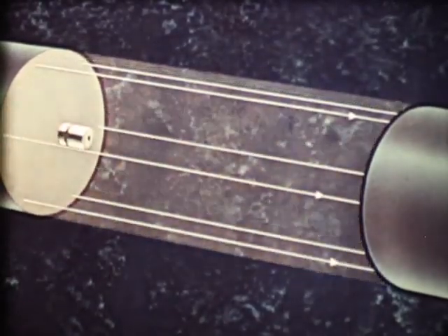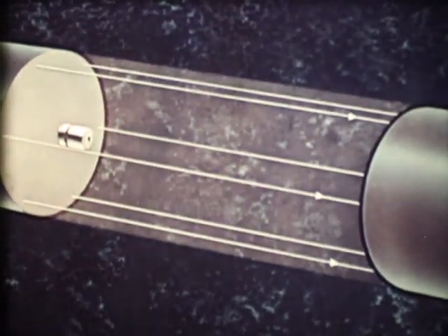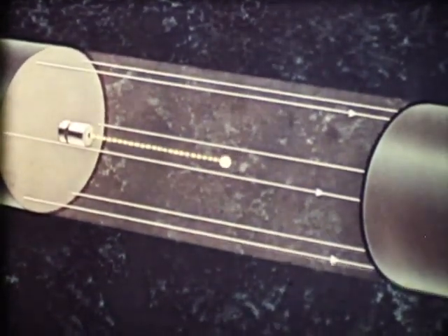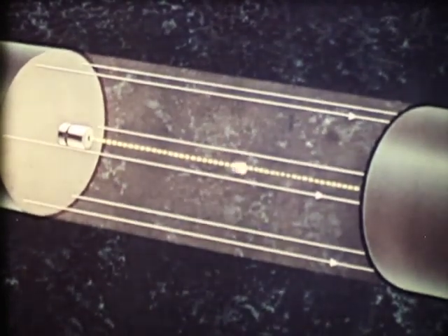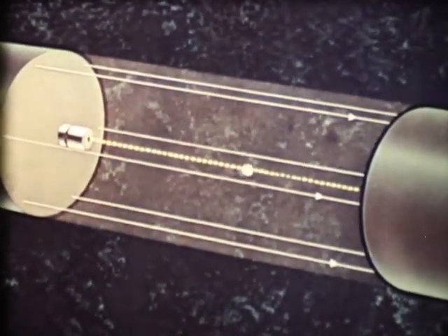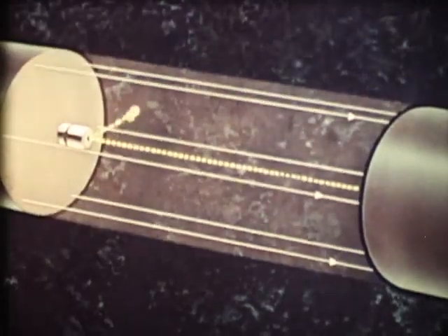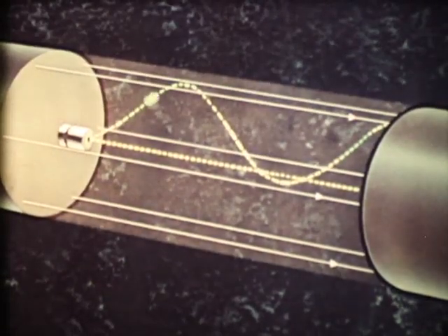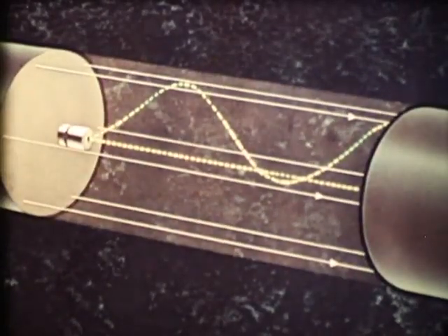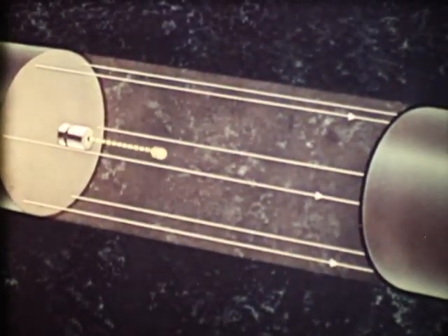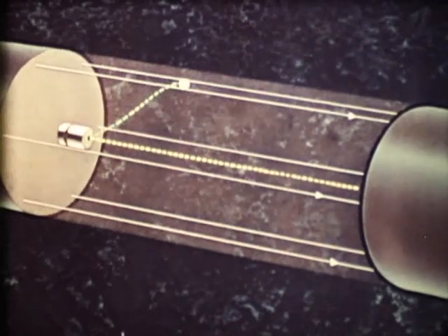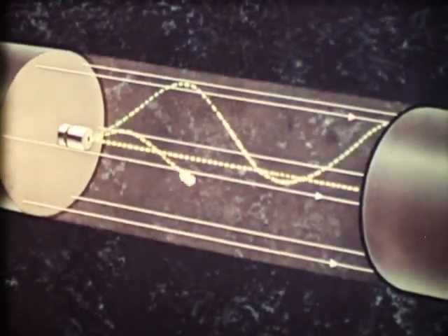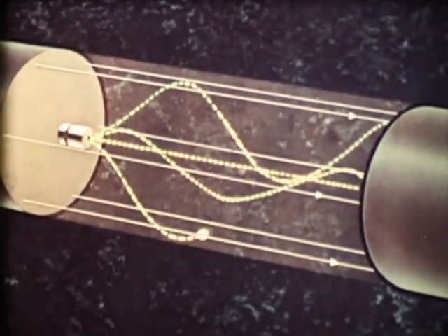In the camera tube, the gun is positioned along the axis of the magnetic field, and you will see that some of the electrons travel parallel to the lines of force. Other electrons will spread out and move along a helical path, passing through the axis of the field on completion of each loop. The velocity of the electrons is such that they all pass through the same point on the axis. Thus, the beam is focused.